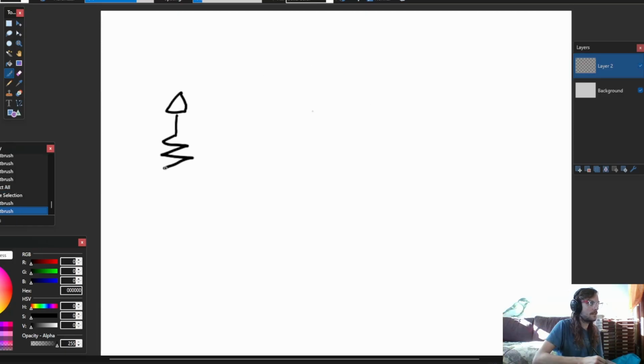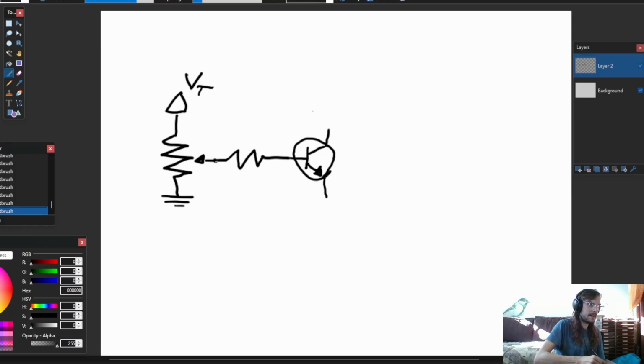To change the values of the incoming current, I use the potentiometer in the form of a trim pot that is connected to the high voltage, which I'm gonna call VT. Then I send this through another resistor to the base of my transistor. And here I add my first 2 Arduino pins. With the Arduino analog pins, you can calculate the voltage compared to ground.